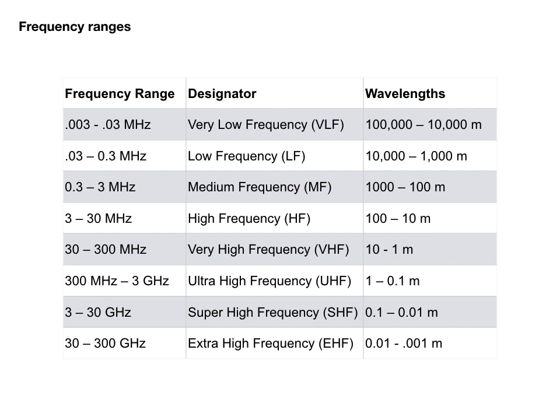As a way to quickly refer to different portions of the electromagnetic spectrum, scientists and engineers have come up with the designations shown in this chart. While these designations are somewhat artificial, they are a quick way to refer to different portions of the spectrum, and quite often, the frequencies within each section have common characteristics and applications. For example, the HF frequencies are often used for long-distance worldwide communications, while the VHF and UHF frequencies are used for local communications.